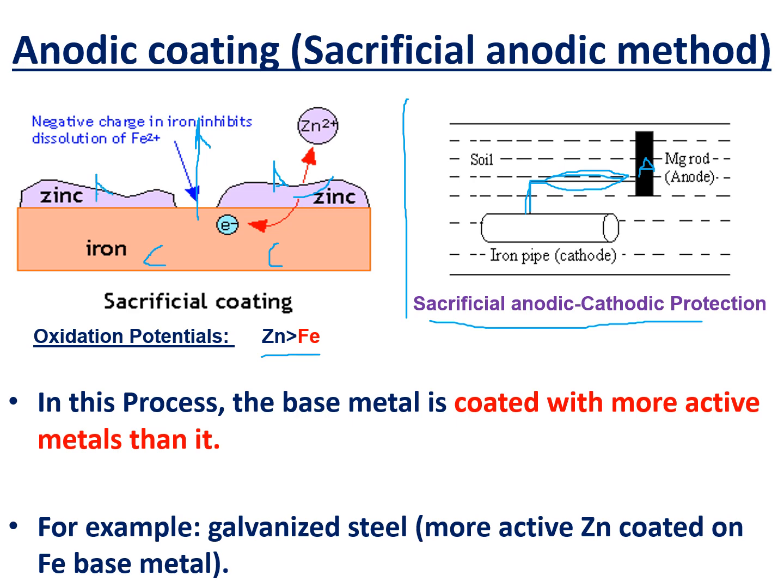There are two different metals, different spots, anodic spot and cathodic spot, and atmospheric gases or moisture. So who is involved in corrosion? Always the anode only is involved in corrosion. Even though damage happens, only zinc is involved in corrosion. Until the zinc is used up completely, iron never gets involved in corrosion. Only after total destruction of zinc does iron get involved in corrosion. That's why zinc sacrifices itself to protect the iron material, and that's why it is called sacrificial coating.